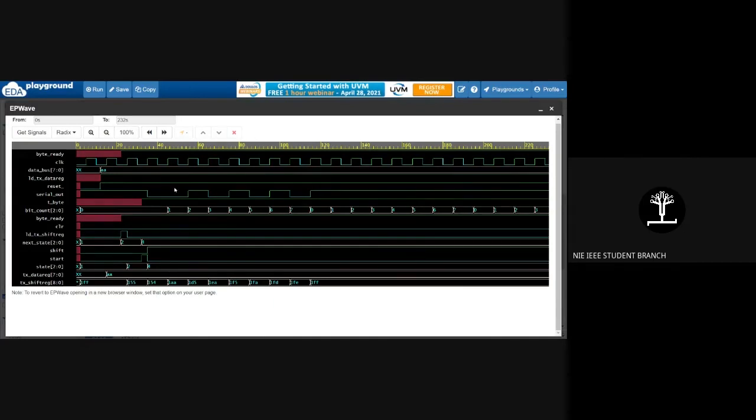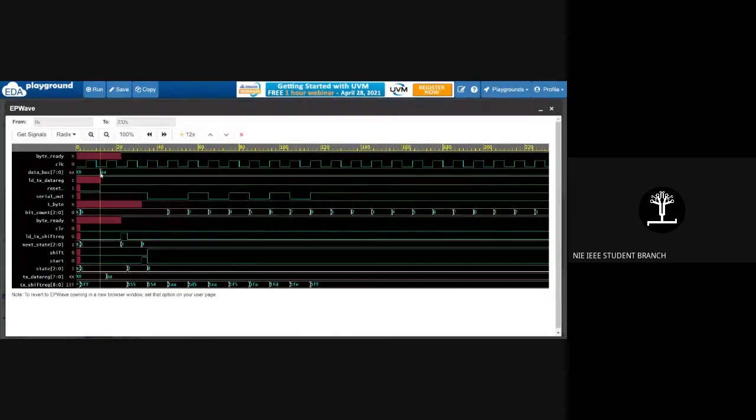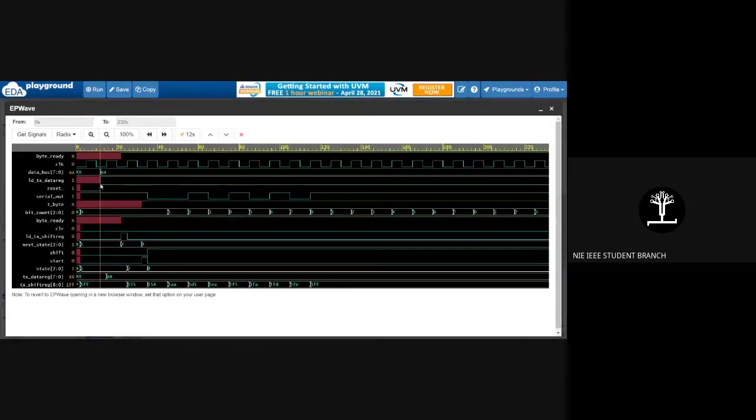Now, if you see at the 12th second, when you see the data bus here, it has literally nothing, XX unknown value. And at the 12th second, it is getting the value of AA. Now, why at 12 seconds? Can you see this? 2 plus 10, that's when reset goes low. And at the same time, we are giving data bus equal to AA. So you get the value of AA, and then it's there on the bus all the time. And here, at the same time, I pull the reset high again, so things become deactivated. And that's when I can start things.